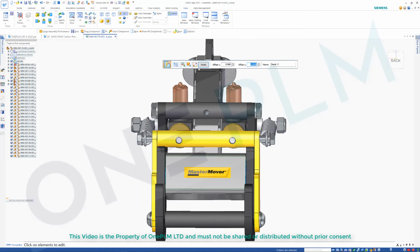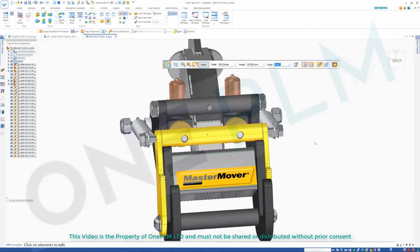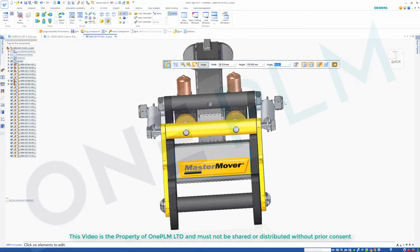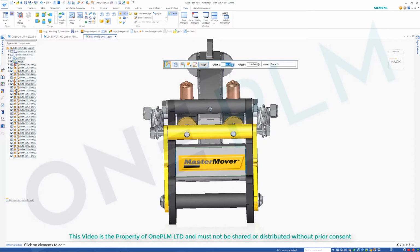Okay, so I'm going to click back onto here. When we do resize, this time I'm going to relock that, and I want to make this a little bit wider, about 100 mil wide. That's got the right kind of size. If you find it does disappear, shrink it back down to close to the original size. That allows you to see roughly where it is. Then I switch back on here and move that back on there. If we do that, it's going to go a little bit too far across, so we can go in there and change that manually.